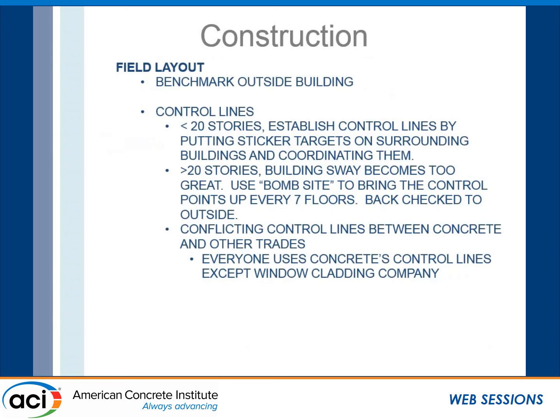And just a few words about field layout. Our benchmark, we're always bringing it in from the outside of the building, and we continue to do that throughout the whole project. Of course, the building is moving as we go up, so a benchmark you had initially brought up is changing because the building is shortening, so it has to be continuously updated. For buildings less than 20 stories, we typically like to provide targets around surrounding buildings and take shots off them and coordinate those to bring our control lines.